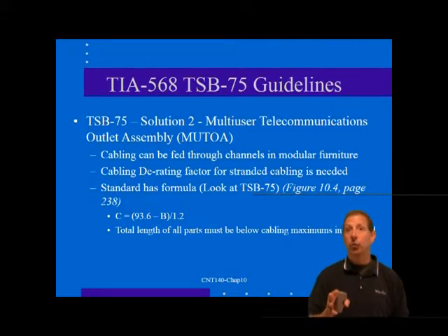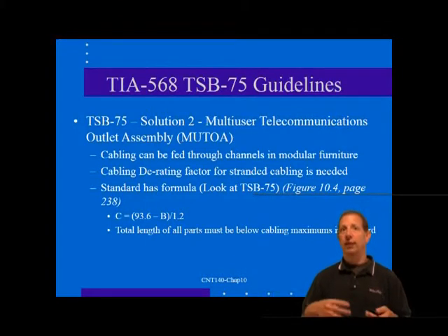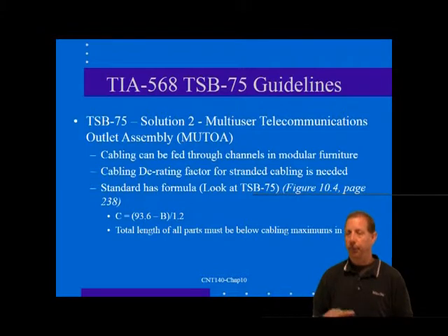However, at the maximum user cord length of 20 meters, only 70 meters of horizontal cable would then be allowed, rather than the expected 75. The reason is the 20% greater attenuation loss for the stranded user cable. The total length allowed for the channel in open office wiring is always at or below the length in normal horizontal lengths. In testing a link that uses the consolidation point method, the normal tests for basic link and channel are still completely valid.